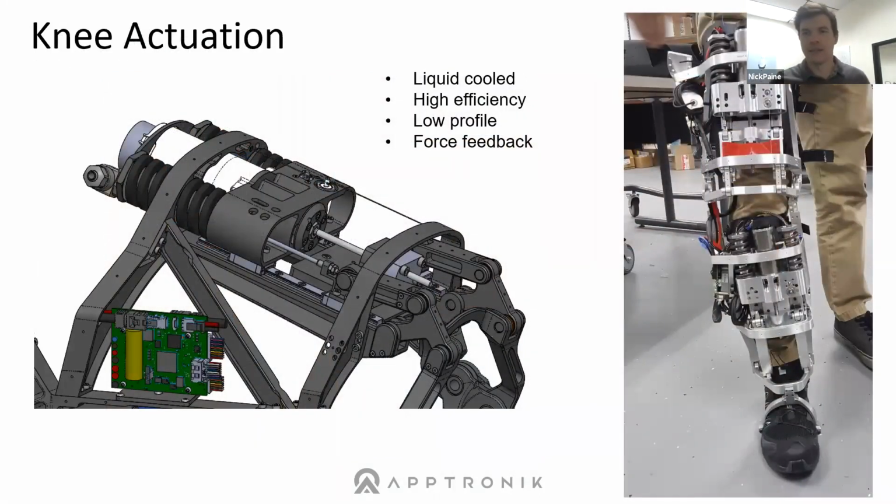This is the leg, the structure and the actuation approach for the knee and the ankle degrees of freedom. You can see that the two actuators for the knee and the ankle are pretty similar. The design requirements for this were pretty stringent, so there's a lot of kind of engineering rigor that went into optimizing this design. Things that we considered, obviously maximizing the torque and the speed that the system can produce, and thus the mechanical power, minimizing power consumption, so trying to maximize power efficiency, and that kind of drove us towards linear drive actuators instead of rotary rotational drive actuators.